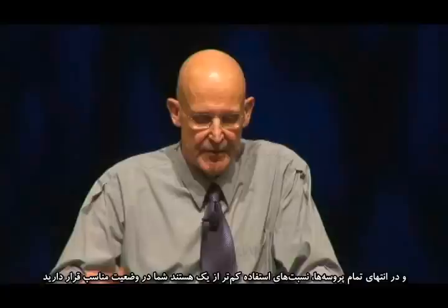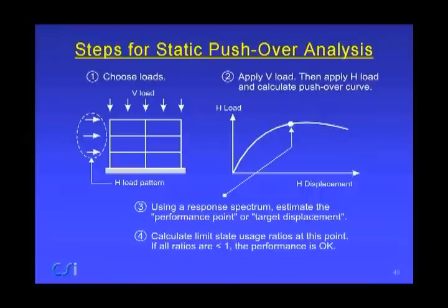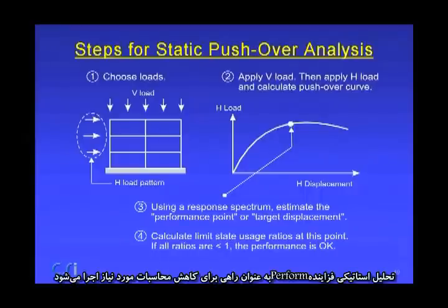At the very end of the process, if all the usage ratios are less than 1, you're okay. Otherwise, you've got to redesign or sharpen some pencils. That's dynamic analysis. It's a straightforward process, but it does require that you use ground motions and rather complicated and possibly time-consuming analysis. Static pushover analysis has been around as a way to